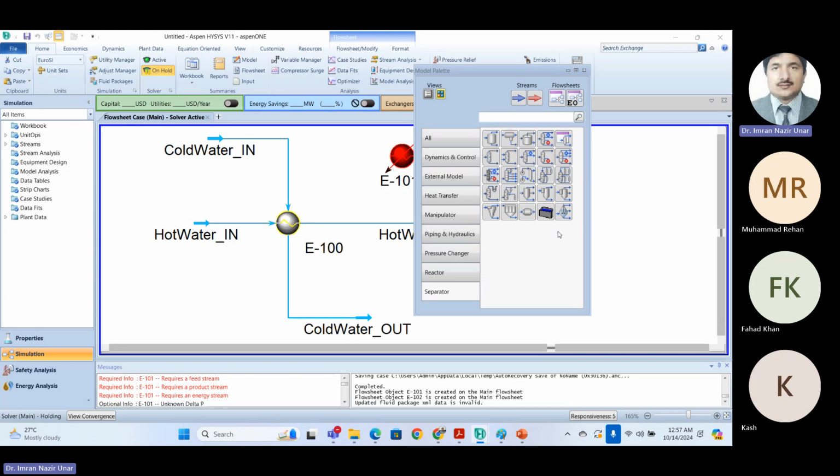And our task is to use that product in the pharmaceutical industry. Now, distillation is possible, but it is conducted at more than 200 degrees centigrade, and we cannot go beyond 50 degrees centigrade. So we use liquid extraction. We first leach out this particular substance into other substances, and then we can separate things.